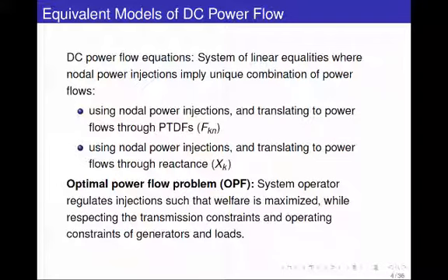What's changed compared to the economic dispatch problem is that now we have a network of buses and transmission lines, and how we inject power in the different buses. We saw there's a linear mapping of how we decide to inject power in each location and how much power we're going to get in each line. You tell me what the power is that you inject in each location, I can tell you how much power is going to flow over each line of the network.